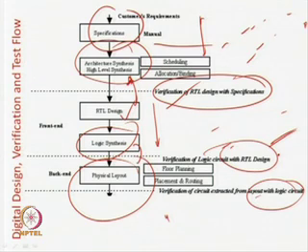Like here we have the logic synthesis, that means now you have a gate level, and what you get at the physical layout is that everything has been laid out as a circuit and interconnection has been done. So, again you have to find out whether this translation was equivalent or not. If the translations are not equivalence preserving, then there is deviation in the design, because you have designed something here, it has changed in the next stage and you may not be able to meet the specification.